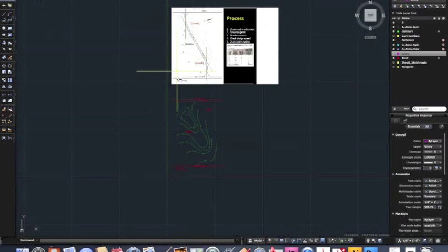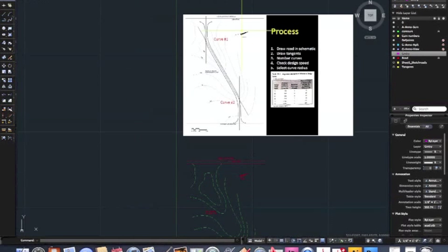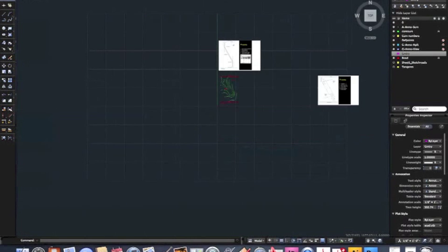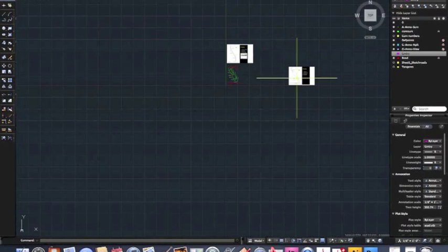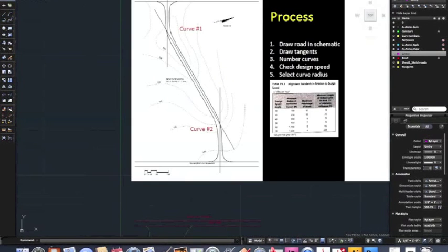Okay, we're going to be doing an AutoCAD tutorial for horizontal curve or horizontal alignment of a roadway today. I'm going to arbitrarily pick a 30 mile an hour design speed here in this table, and we're going to be working with a 20-foot wide road based on the class example that we're going to be going through. The process has been laid out in 2 steps for us by Paul, so we're just going to follow through and see if we can get it to work in CAD.